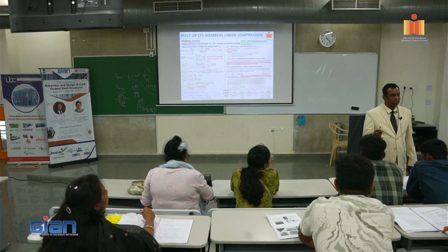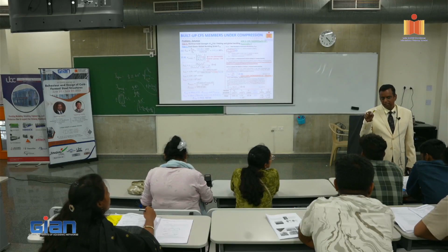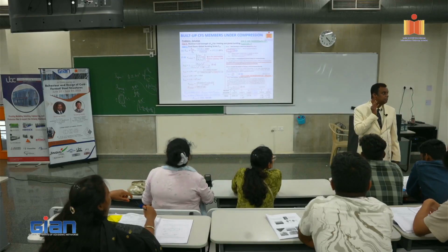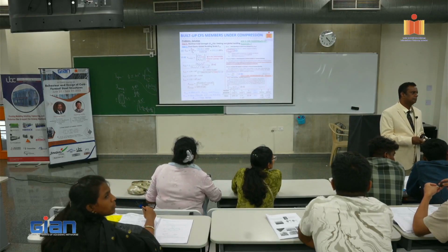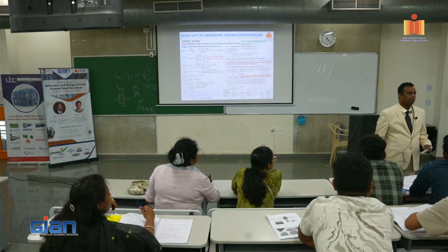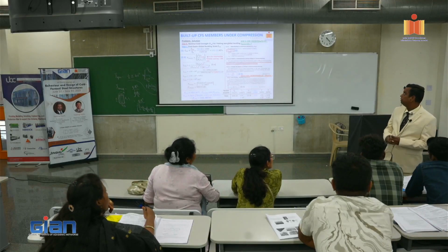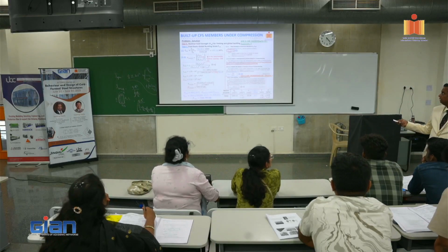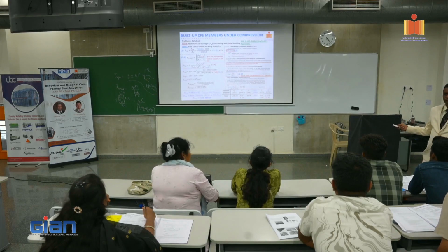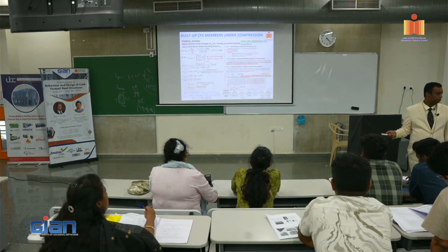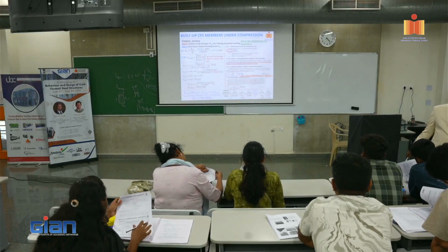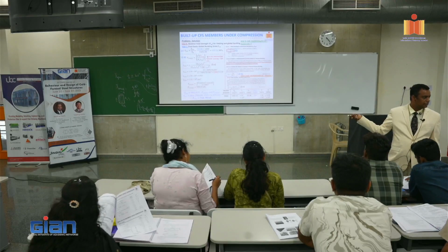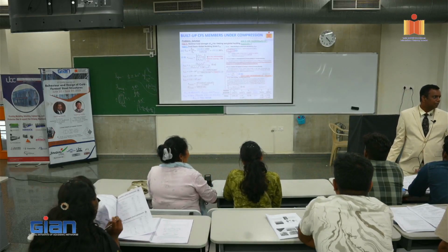Now, what does critical mean, FCRE? Whenever they say critical, what does it mean, critical, CR? Huh? Minimum load or stress which will lead to the failure of the member. You say that it is critical stress. It is not minimum, no. How is 494 minimum? It is exceeding the yield, right? What is the yield for this problem? 450 something? What is the yield stress? 350 is the yield stress. So according to your logic, it is exceeding the yield stress. How is it correct?